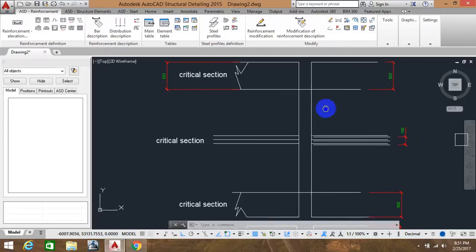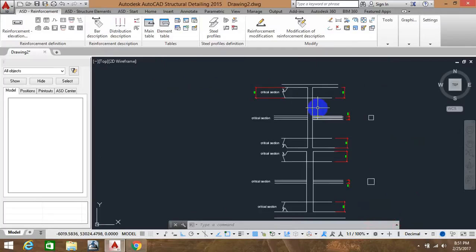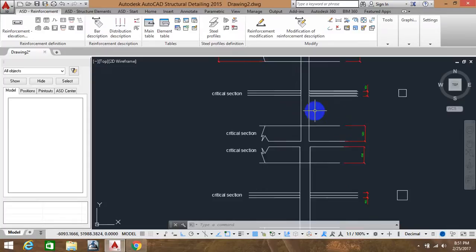Another thing: here we have Ld, the development length, which is 15 times the diameter of the main bar, according to IS 456. These are the things I want to clear up before I detail this one. Another thing is that the minimum permissible percentage of reinforcement according to the gross area of concrete is 0.8% minimum and 4% maximum. In the code you can also see 6%. This 6% applies wherever you have a lap splice.